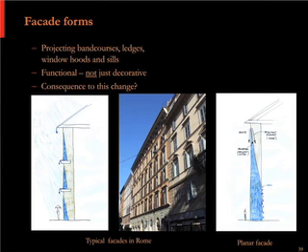Unlike thin wall systems today that have a backup waterproofing or a drainage plane, this is all it is. It's a thick-walled masonry building, and our buildings in Boston, Beacon Hill, Back Bay, all the red brick buildings, basically work on the same principle, although they tend to be only about a foot thick. A lot of these buildings in Rome, the walls are several feet thick. But they work the same way.